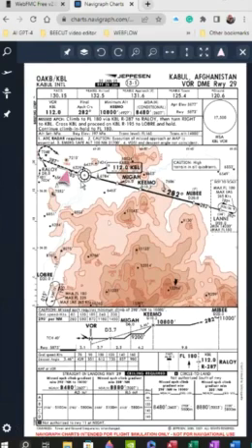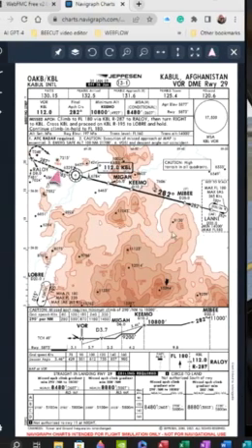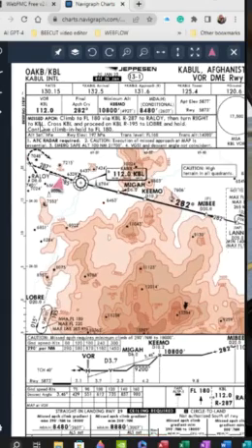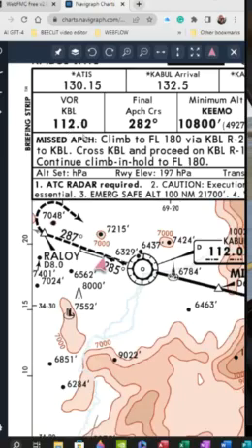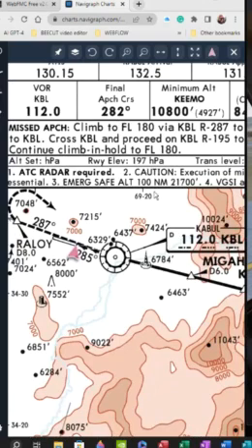In our case today, we will take off of runway 29, come back over the VOR, and then on vectors to parallel the 102 radial outside of Lanny at 14,000 feet and intercept the VOR DME approach, that is, intercept the 102 radial. So the Kabul VOR is 112.2, and the inbound course will be 282.